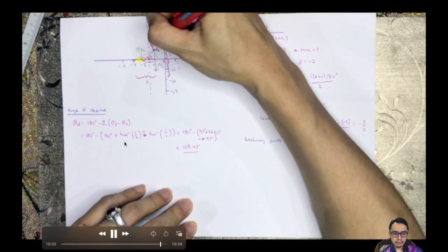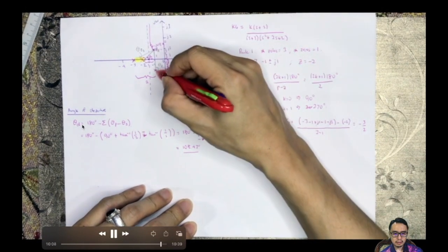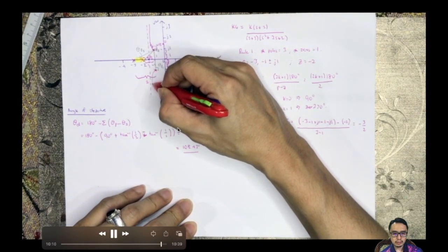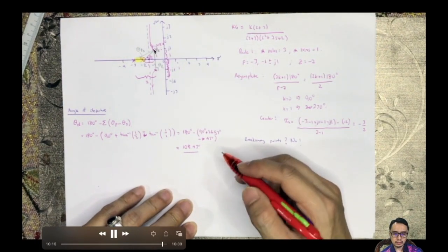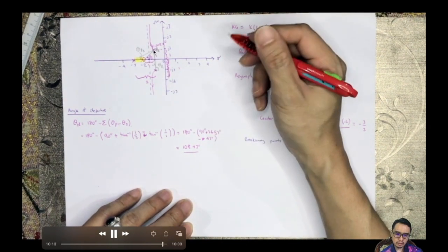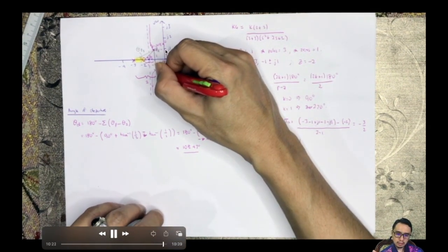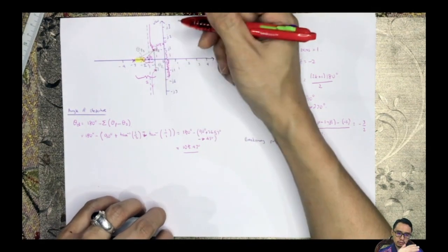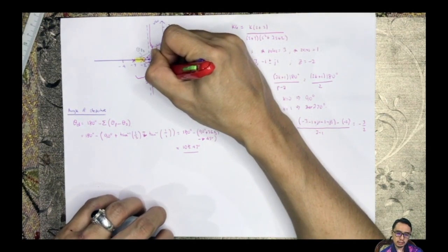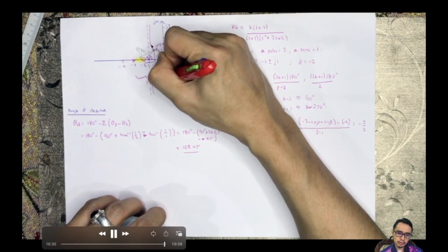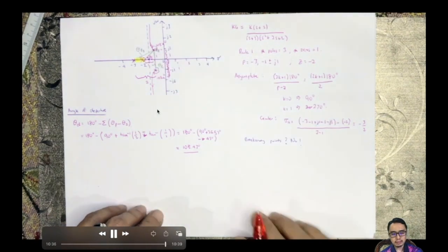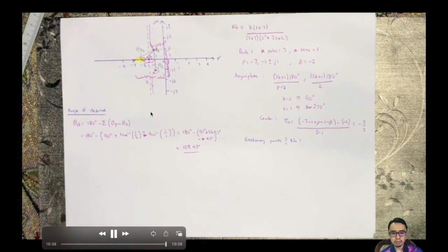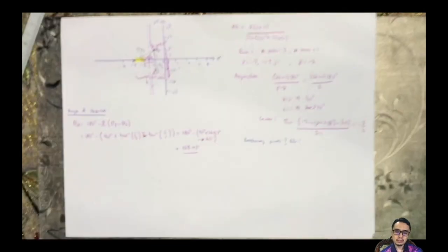So you will see that the angle made by the locus leaving this particular point is 108.43 degrees. So that's 90, so it's a little bit more than 90. So it's like 108 degrees from the real axis. So you go counterclockwise 108 degrees. It will leave this particular point approaching the asymptote. So you don't have to calculate for the bottom part because it's going to be the mirror image, the second rule, if you remember. Right? So that's the case when we have the angle of departure.